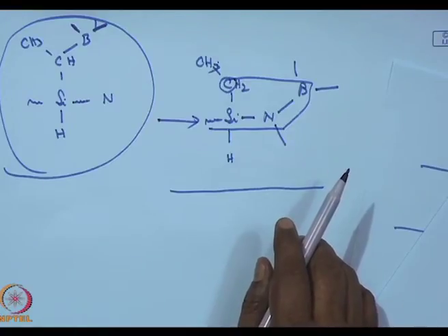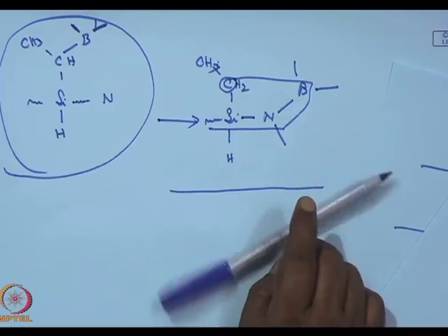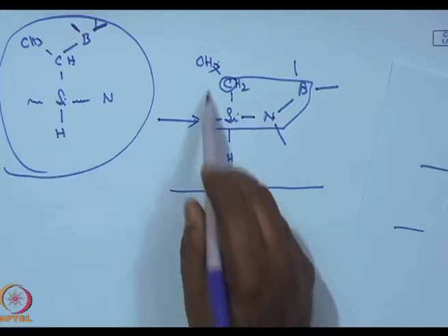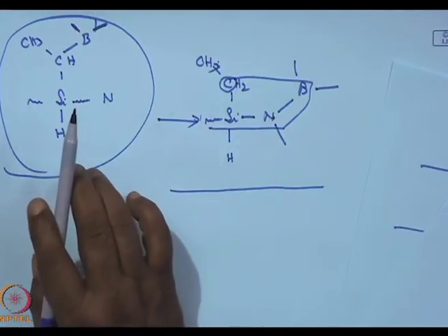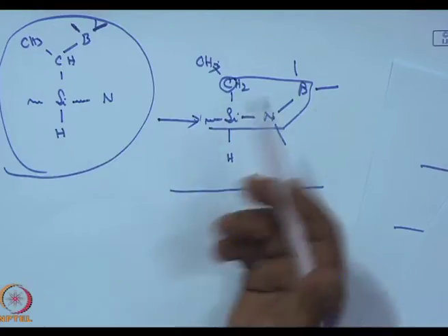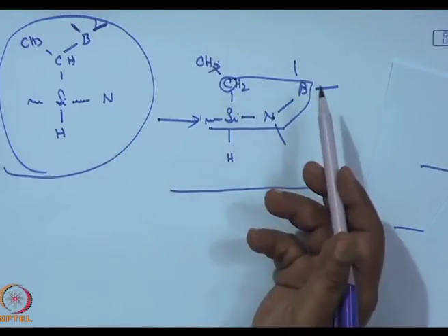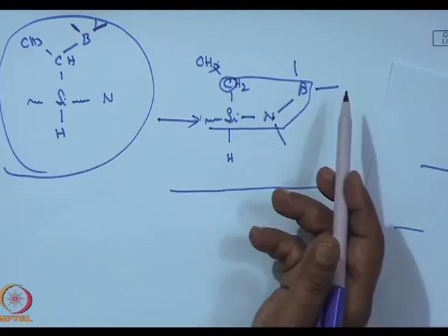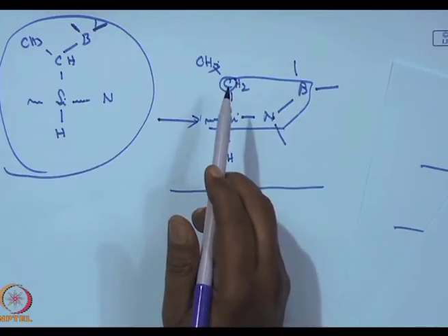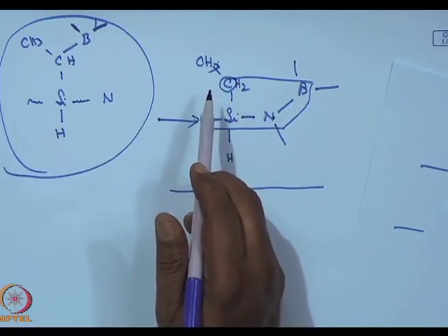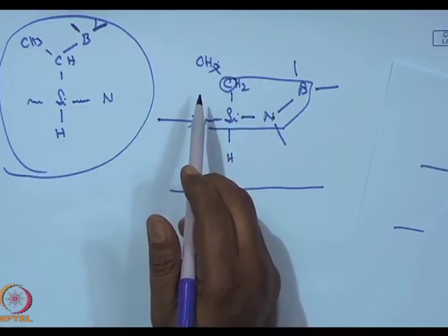And hence, in this particular case, we have a real strengthening of whether you call this a silicon nitride matrix or a silicon carbide matrix. It depends, it's a mixture of both, with another one with boron carbide or boron nitride, what I had written earlier, through the precursor-derived polymer ceramics route.